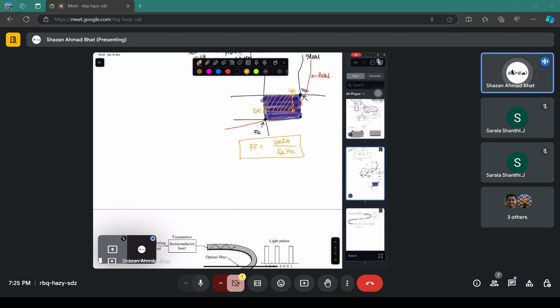Okay, so this fill factor, you want to ensure that it is approximately equivalent to 1. It will be 1 when Vm Im is equivalent to Isc Voc, when both quantities are equal. So ideally you want this to be a square form in order to increase this particular fill factor, which determines basically the efficiency of a solar cell.